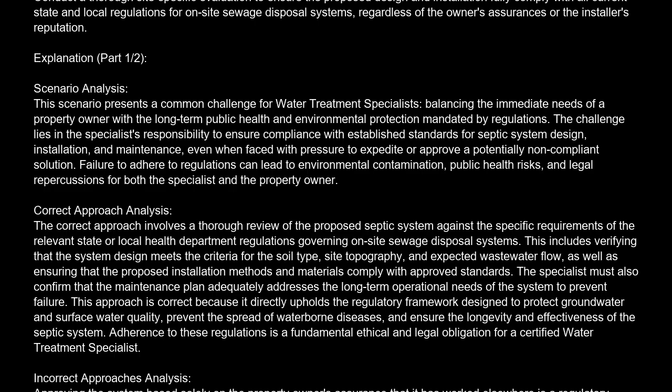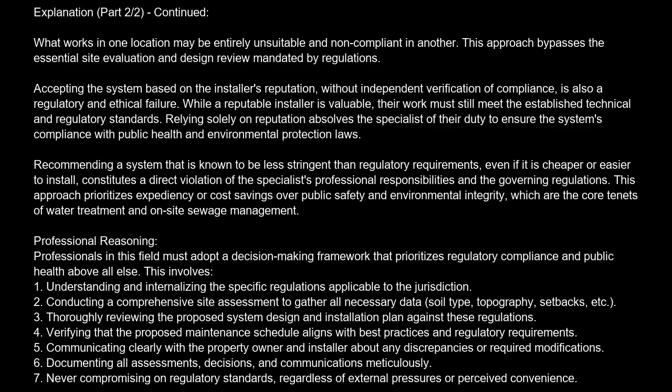Incorrect approaches analysis. Approving the system based solely on the property owner's assurance that it has worked elsewhere is a regulatory failure. Septic system performance is highly site-specific, dependent on local soil conditions, groundwater levels, and climate, which vary significantly. What works in one location may be entirely unsuitable and non-compliant in another. This approach bypasses the essential site evaluation and design review mandated by regulations.